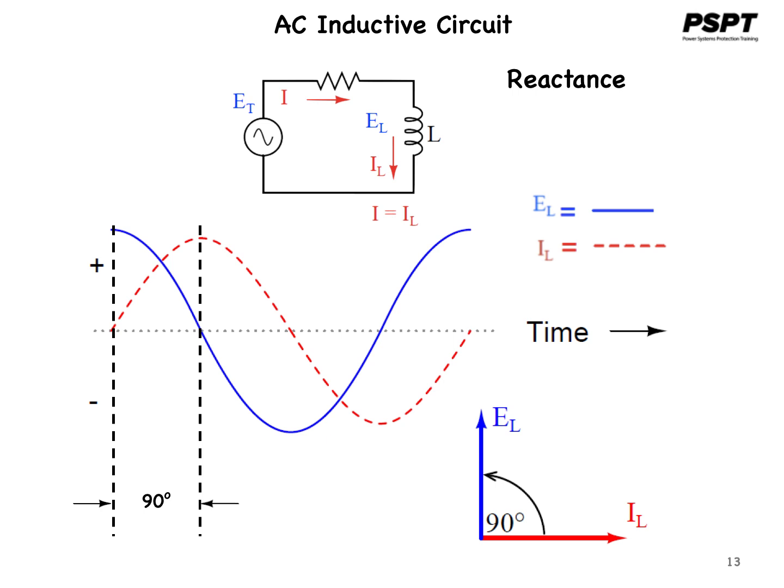Reactance to AC is expressed in ohms, just as resistance is, except that it is indicated with a different mathematical symbol, X instead of R. To be specific, reactance associated with an inductor is usually symbolized by a capital letter X with a letter L as a subscript following it, like this.